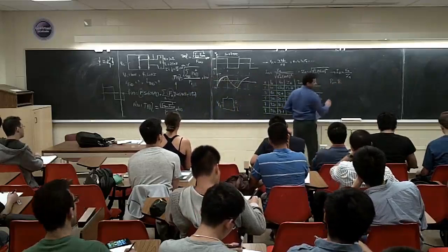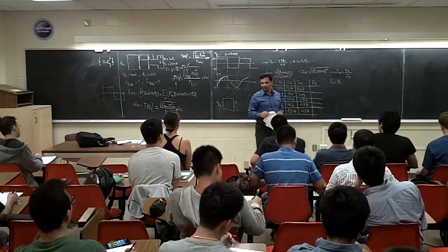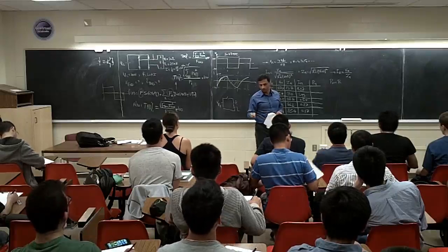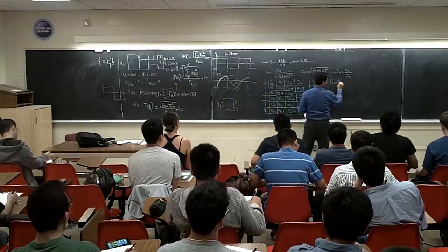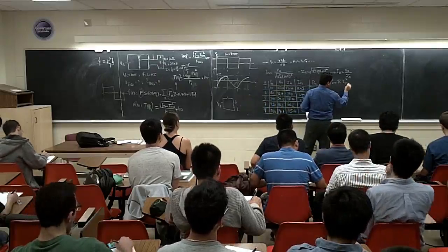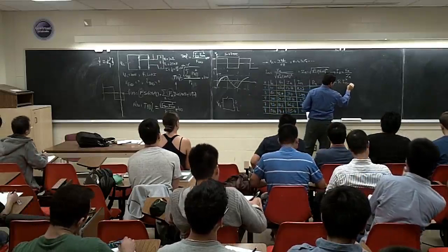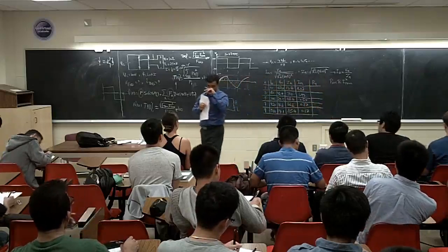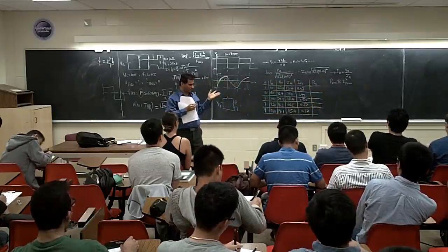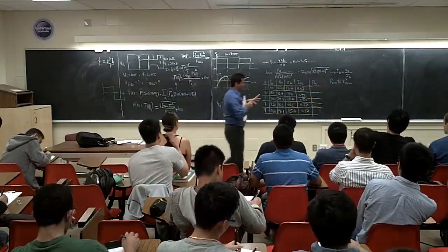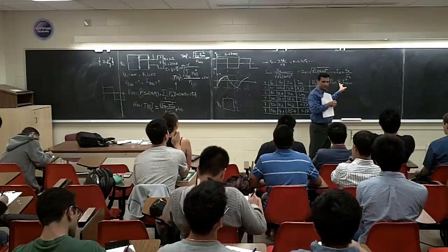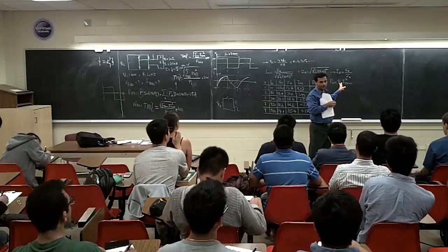It's going to be R. Do I need to write Rn or not? Does R care about the frequency or not? No. So basically, it's going to be R I_n to the power of 2, but RMS. I should put the RMS value also, right? This is a resistor, the power is going to be R I_RMS to the power of 2. But I said, does this one care about the frequency? Or it does. Not here.